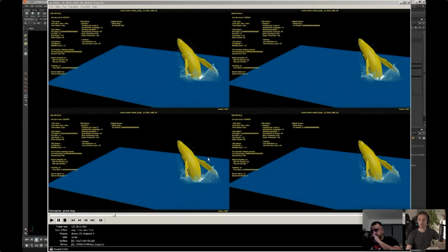Even if it's a small value, it can give you that sense that your splash is not going crazy high. The smaller droplets will be slower. So even with a small value on the simple pop drag node, that can immediately sell that there is some air drag or wind, even without a wind force.